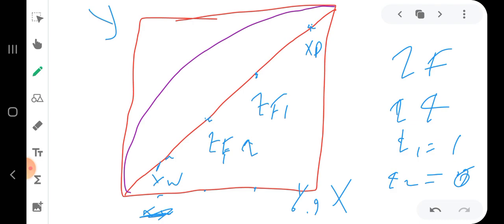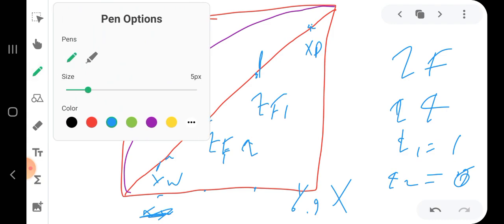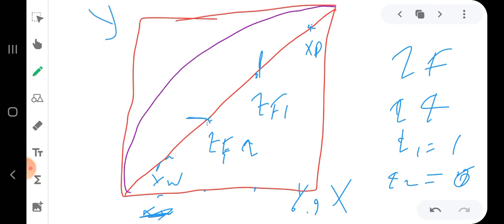For saturated liquid, the line is going to be vertical, as we said in the previous lecture, and for saturated vapor, the line is going to be horizontal, like this. Then you draw the top section operating line as we discussed in the previous video. Suppose you draw this top section operating line and you get a line like this.